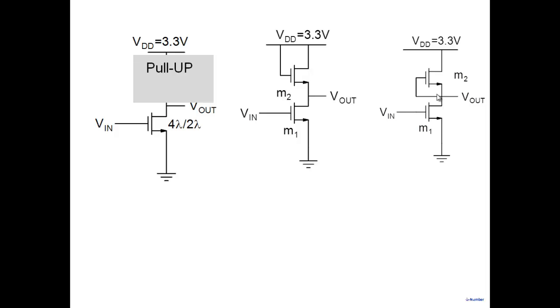Suppose I say make it work. I've taken an NMOS and I've connected this here. Make this work as an inverter. What will you do? Make it work as an inverter. Why did you say it will not work as an inverter? You said gate to source voltage is less than the threshold voltage. So how do I make it greater than threshold voltage when gate to source voltage is 0? Design an NMOS with a negative threshold voltage. If gate to source voltage is 0, make an NMOS with a threshold voltage of minus. Right? Then this will conduct.